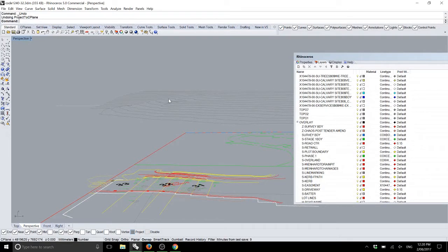We don't know, right? So contours are actually the last thing you want to work with. Unfortunately, we have to work with contours here, so you guys are compromising. What you guys want to be using is spot heights. Spot heights are what are actually used to generate contours by surveyors. What we're about to do with the survey contours is the exact same process surveyors use to generate contours. So they take spot heights, they cut planes through them, just like you guys did with the waffle, yeah? And then they bake the lines out and they send them to the architect, okay? Take a note, in 3 to 5 years' time, however long it takes you to get through this and get into industry, if you have the opportunity to talk to a surveyor, you want spot heights, okay? If you have a choice between the two, spot heights, okay?